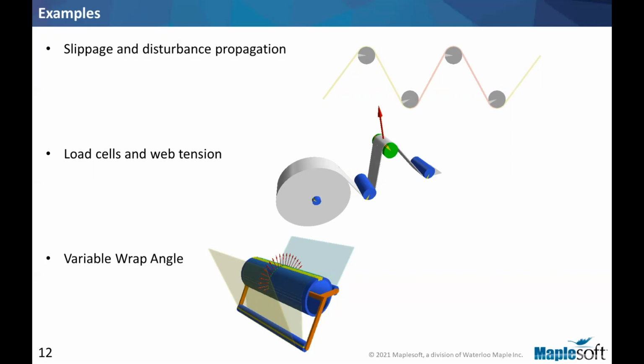We're going to look at a load cell in the second example, and how we can use the reaction applied to the load cell, which will include both the tension and the weight and the angles, and work out the tension, and then check it against the exact answer we get from the simulation itself, and see what factors would cause error in the measurements if we use the load cell.